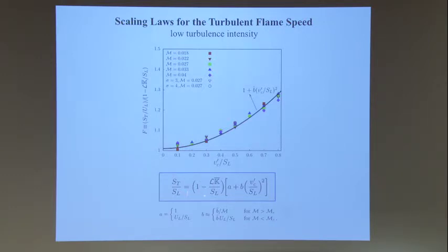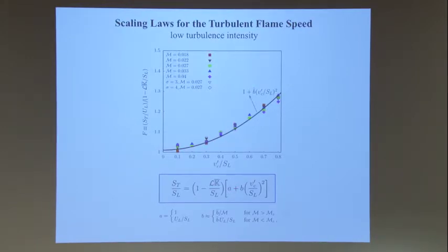So what we argue is that turbulent speed would have a stretching factor that of course depends on the property of the mixture. You see, there is no ad hoc coefficient. Everything is given a certain mixture. I can tell you what the Markstein length is, and I can compute this average stretching from the calculation, because the mean stretch is something that you compute in the Navier-Stokes flame level set calculation. And then you have these coefficients which are indicated here, and you indeed have a quadratic dependence on the coefficient. And of course, these also depend on the heat release, or sigma, as I have shown you earlier.